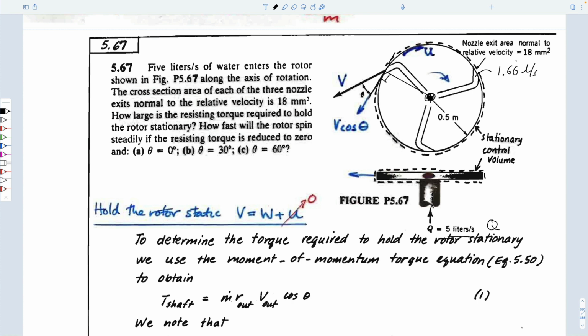If this water comes in here and turns a right angle to go out through this and then out through this plane, because everything in this plane is perpendicular to everything in this plane, it can have no component in this direction. So we don't have to worry about the fluid coming in through here because it's orthogonal to the other ones. Just as in the case of the vane that was being pushed by water arriving in the vane and then going vertically upwards, we don't care about the water going upwards because we're only resolving in the x direction, and that velocity upwards is in the z direction, and its x velocity is therefore 0. So that's the rationale for this.